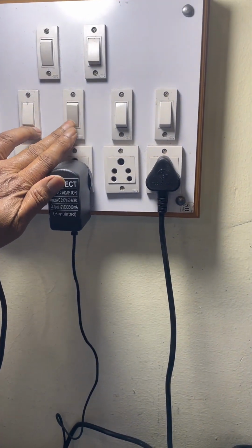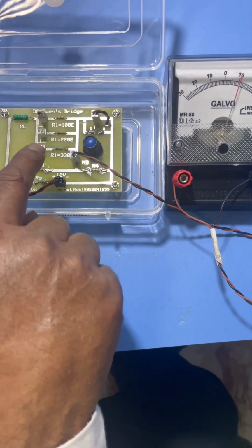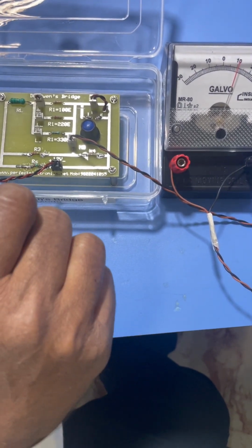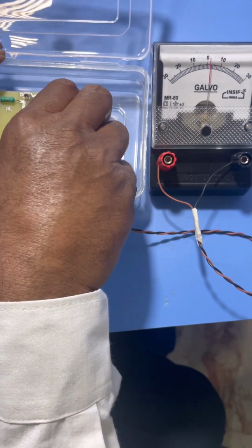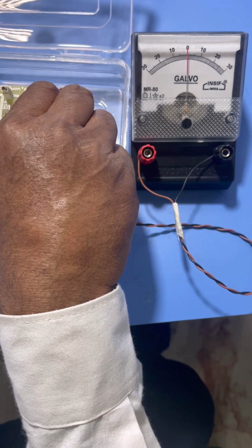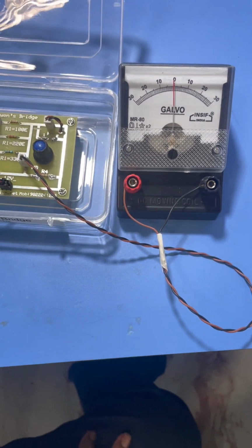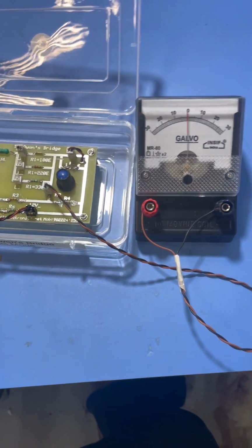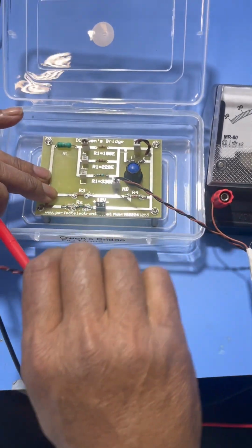See, I am switching this on. Galvanometer shows some deflection. I have selected R1 as 100 ohms resistance. Now we shall balance the bridge by rotating this knob of the potentiometer. So I am putting the pointer of the meter at the zero deflection. Now we shall measure the resistance of the potentiometer by the use of multimeter, by disconnecting this power supply